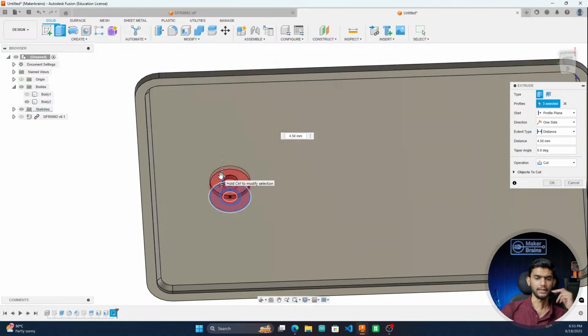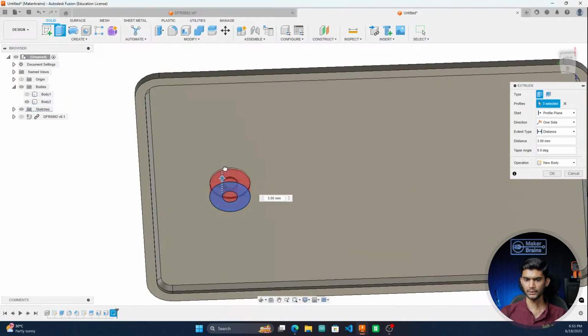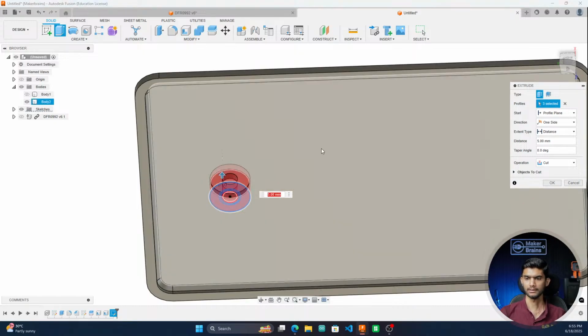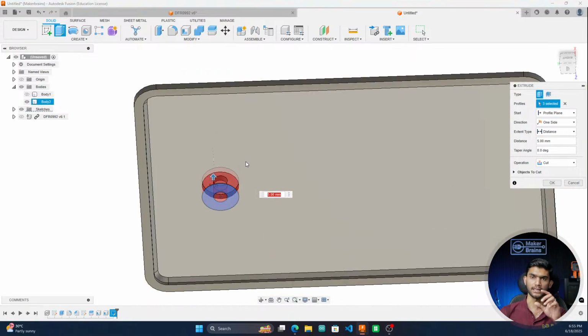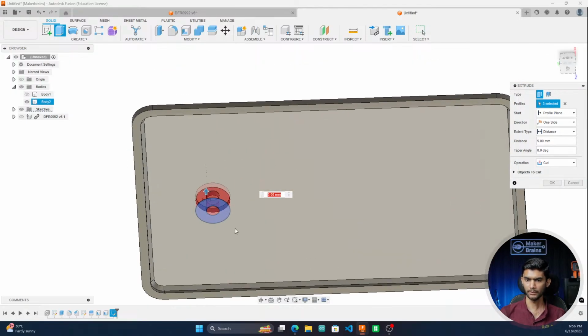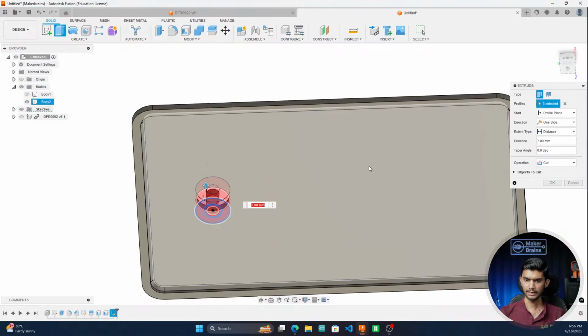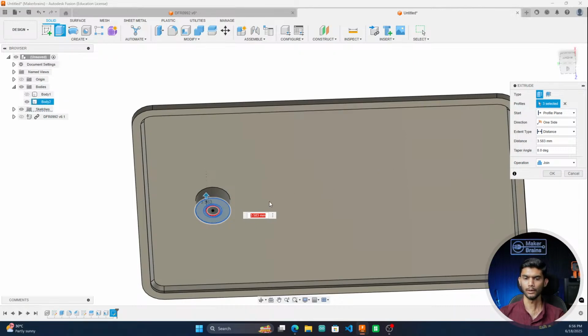If your hole option is not always round, if it is any shape, then you can use this cut option. I'll show you this same feature again when embossing our brand name or any naming on our enclosure. As you can see, I have pulled it to 5 mm, but it need not be 5 mm. I can just pull up to this cover surface. Okay, so I have selected this surface. I can grab it, or I can select the surface to which I want to pull.